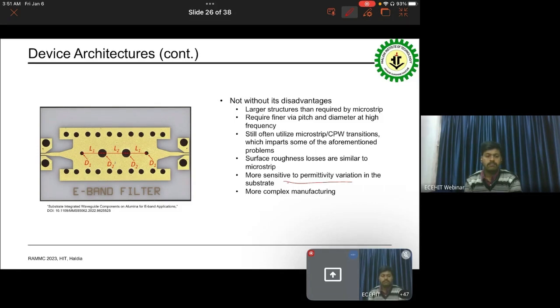In a microstrip, because you have that concept of effective permittivity, it's less of an issue that the substrate's slightly lower because you're spending a portion of that time in a different permittivity. There is a lower percentage decrease or increase in the permittivity using microstrip, that effective permittivity, versus the substrate integrated waveguide where the entire field is sitting inside of that substrate. So if my permittivity is 9.3 versus a specified 9.6, that's going to cause some performance issues.